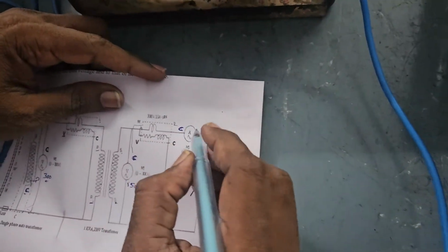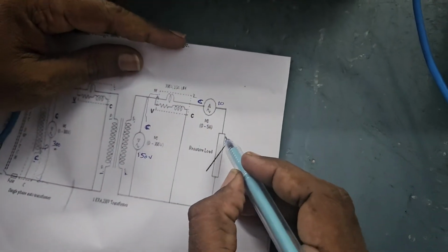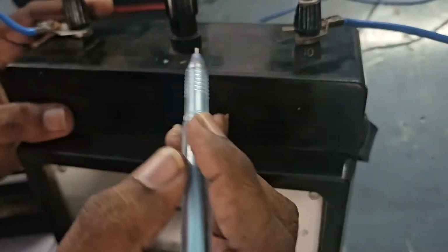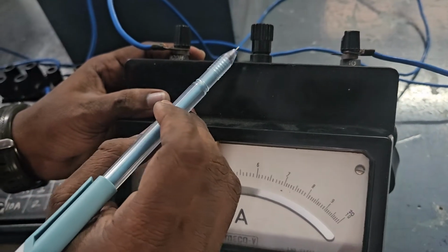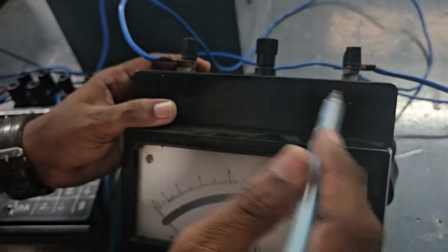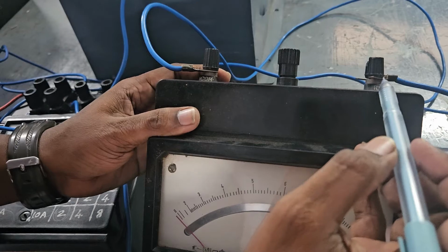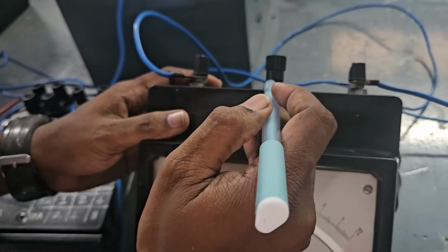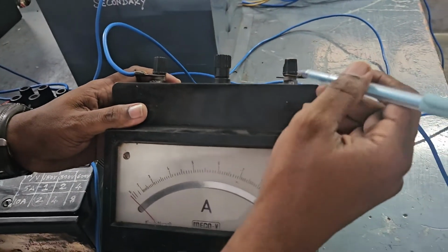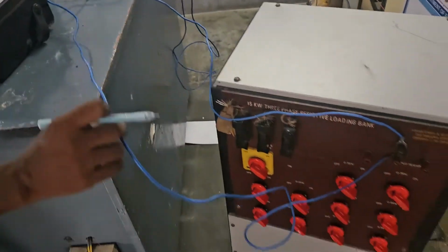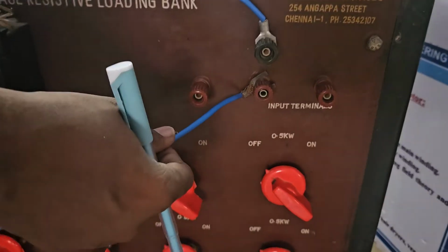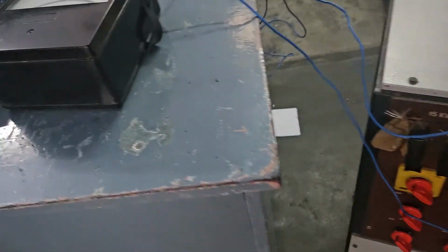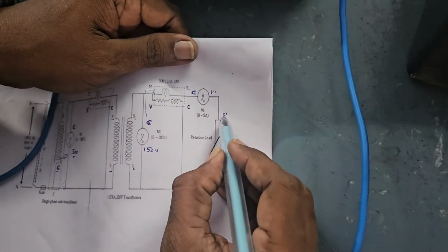Okay, and then I'll connect the ammeter range terminal to the electrical load, that is the resistive load phase terminal. You see again I have two ranges, 10 ampere and 20 ampere. Based on my load level, my current is not going to exceed 10 ampere, so I'll keep to the 10 ampere range. But if you want to take from 20 ampere, that is nothing wrong. So I am taking from 10 ampere. That 10 ampere terminal is connected to the resistive load phase terminal.